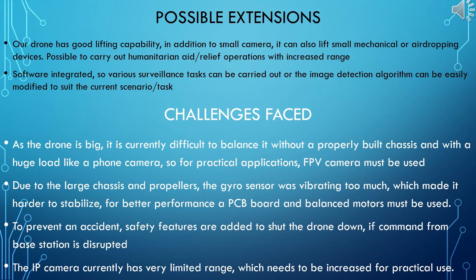And here are some challenges we faced during this project. As the drone is big, it is currently very difficult to balance it with a properly built chassis and with a huge load like the phone camera. So for practical applications, an FPV camera must be used.